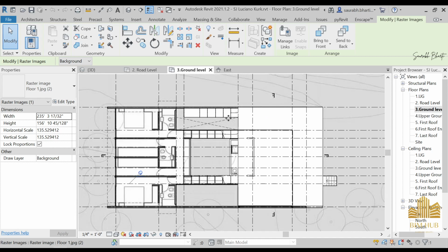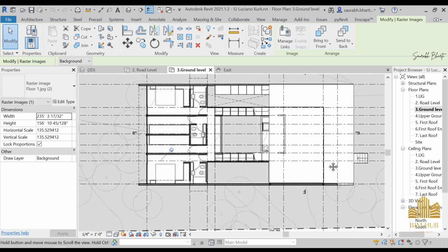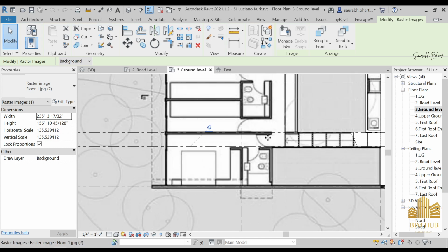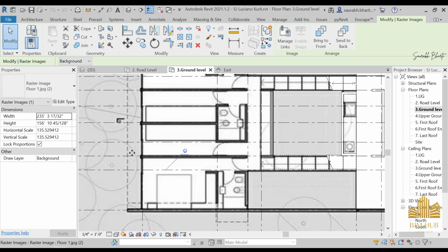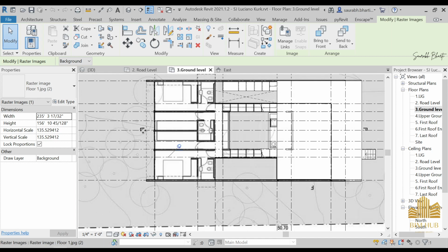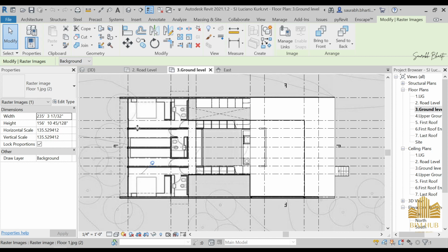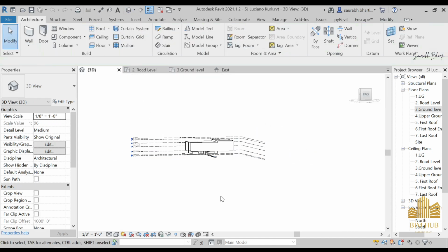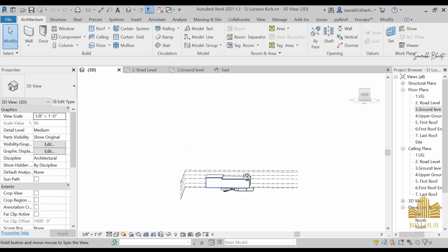So 9 inches wall on this side, 9 inches wall on this side, and after that 4.5 inches as the internal wall. So these walls that you can see in the inner part of the building are just 4.5 inches, and these are our curtain walls. So I drew everything by the grids, and yesterday we had this result.